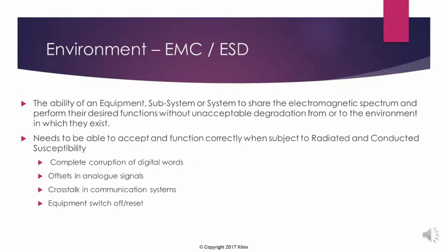So an area as well that we need to consider is EMC and ESD. ESD is very much a system level electrostatic discharge. If we're lucky, we only have to deal with the human body model. If we're very unlucky, then we have to deal with the helicopter environment or something like that. But that's very much done at the electrical level, at the board level, to ensure that any energy is dissipated to the chassis as easily as possible and doesn't propagate into the devices.